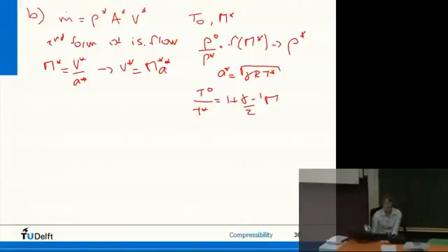Yeah? So the crucial thing to realize here is that you don't have many conditions at the throat. We do have the area, so we have no choice but to compute the mass flow through the throat, the only place where we have the area given. But we do have information on the Mach number, and that can give us a lot of information on the temperature, pressures, and densities, okay?